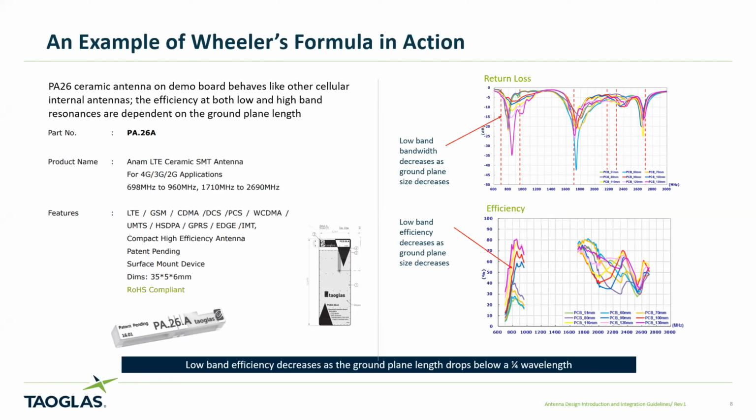What we're showing here is a demonstration board and an antenna. You can buy this on DigiKey, and other antenna companies have it. It's a common tool for developers to get a hold of an antenna and see if it's going to fit their application. This is a common cut down test, and the idea is to educate a customer. As I reduce the length of the ground plane that the antenna is on, I'm not changing the antenna volume, but I am changing the ground plane that the antenna is driven on. That ground plane is the multi-layer PCB of the radio system you're designing for this client device. As you reduce the ground plane at the lower frequencies, you can see the bandwidth decrease and the efficiency drop. What's happening is that at lower frequencies, the physical volume that the antenna occupies is not large enough. The antenna mode volume actually encompasses the entire antenna and ground plane structure.